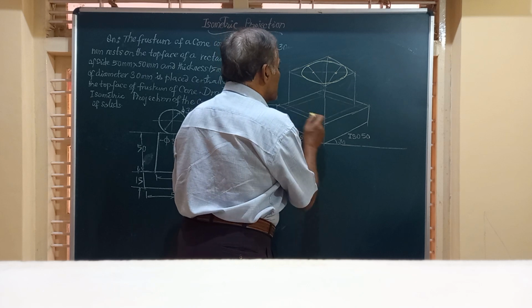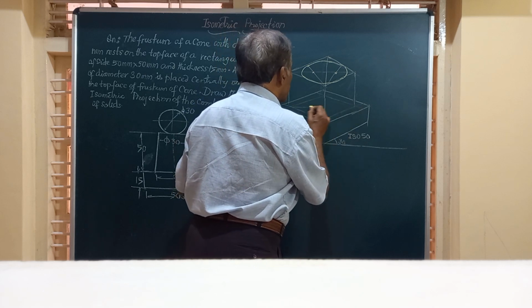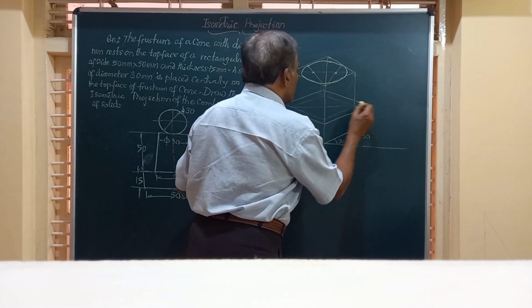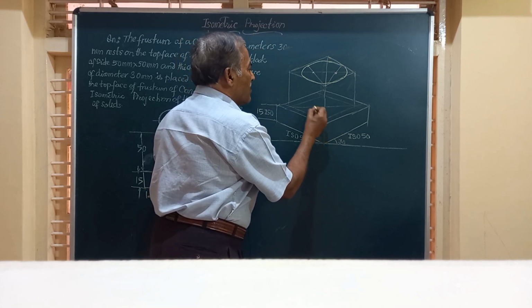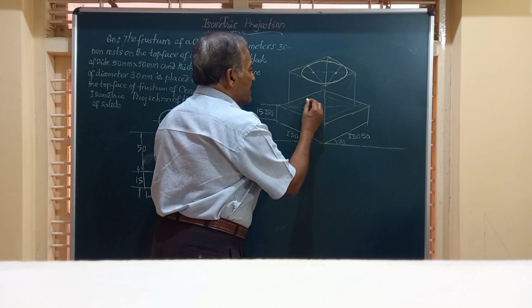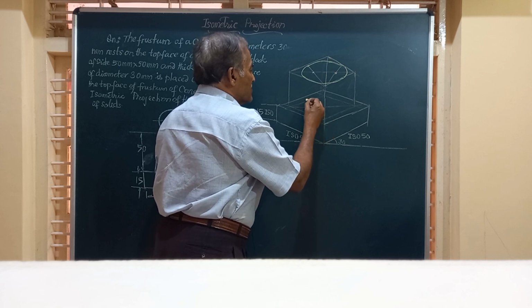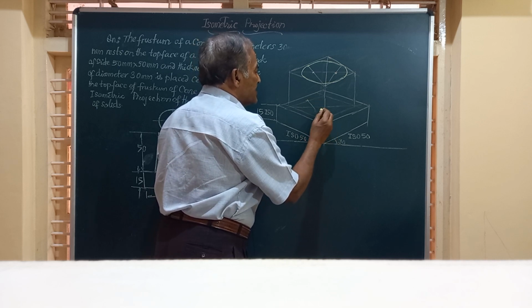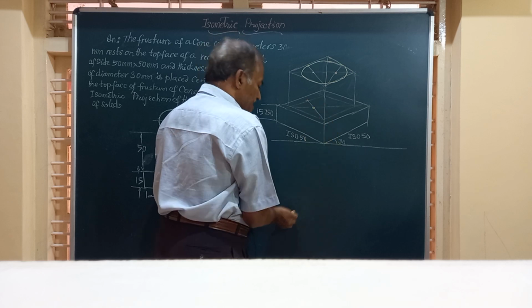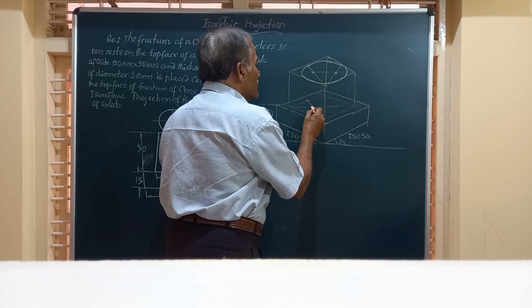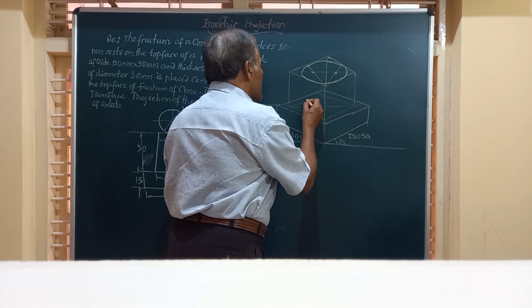So this box is having 40 dia. We follow the same procedure. See, we'll join this to the opposite side center, and it will meet somewhere here. So friends, this is our center C1 for this. The center C1 and radius equal to this much, an arc we draw.